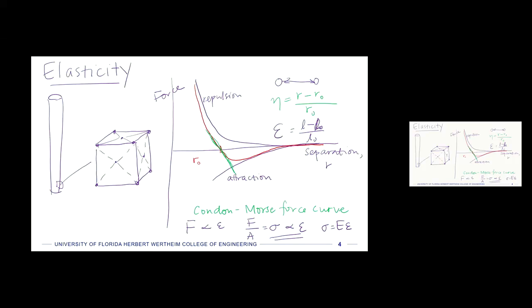But there are many different crystal structures, and depending on which one you have, it'll change these energy or force separation curves, and then it will also vary between materials. There could be two metals or two alloys that have the same crystal structure, but they don't have the same elastic modulus. And so I think I'm going to go with that answer.